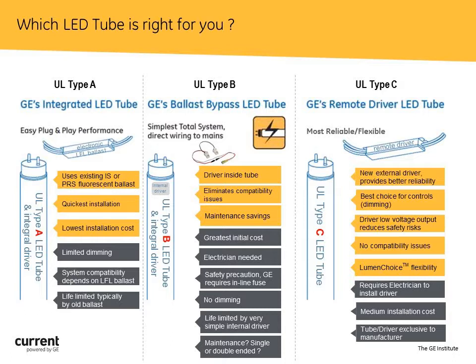If dimming is required, remember on Type A, you've got about the 80-20 rule. In Type B, you have 0 dimmability. So with Type B, even if dimming is needed, as soon as that dimming fluorescent ballast is removed and a Type B wired lamp is directly connected to the line, dimmability is no longer available.